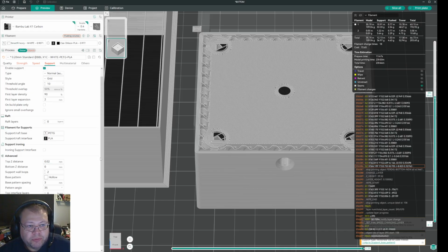Now notice what happens. So this here I have sliced it with a spacing between the two layers. So the two layers in actuality do not have a physical contact, if you can see it like that. If you print, it will get a physical contact because you squish the line, but in the slicer it doesn't really have it. So the slicer doesn't actually realize this. So the slicer here thinks that what you are printing is a bridge over an unsupported area.